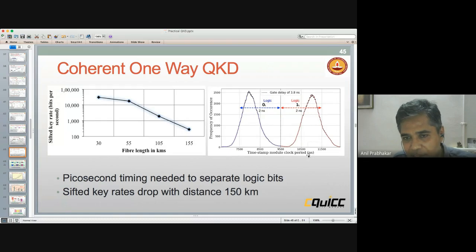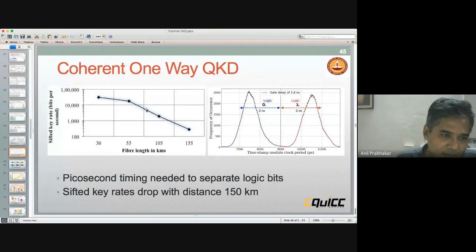It's 100 picosecond. Actually, it's got 55 picosecond resolution. The jitter is what kills us, because the timing jitter between the time to digital converter and the FPGAs is also of the order of tens of picoseconds. So being able to do high precision electronics is the challenge for most of our quantum communications.